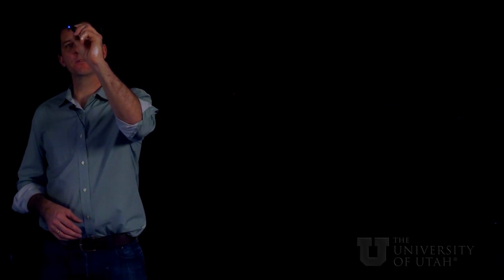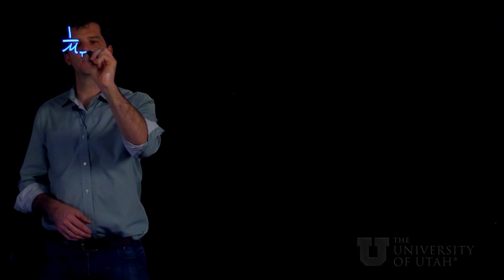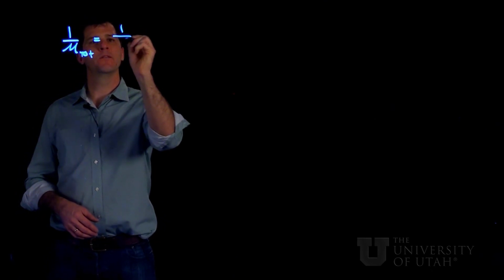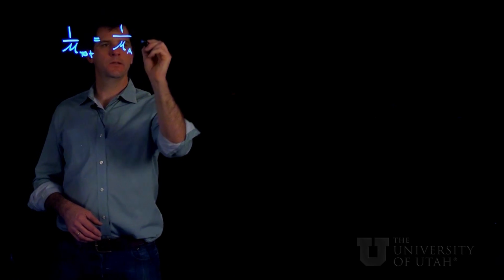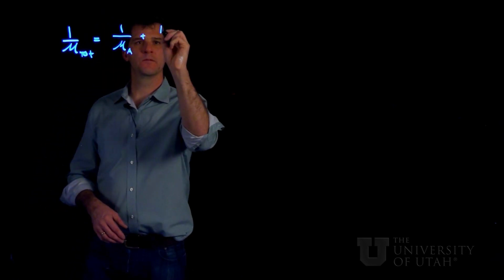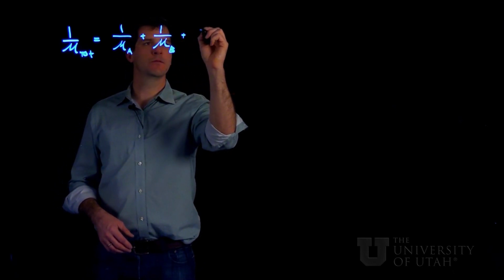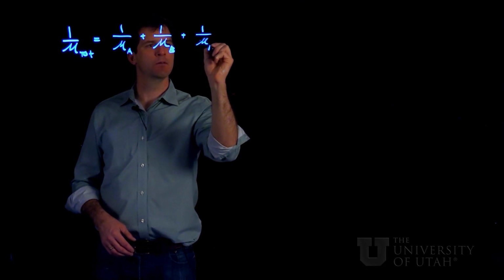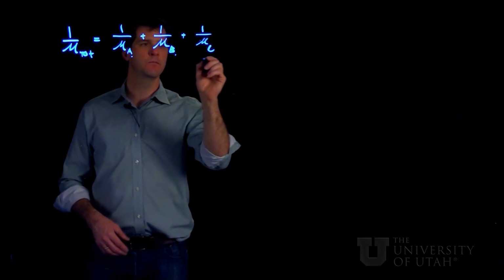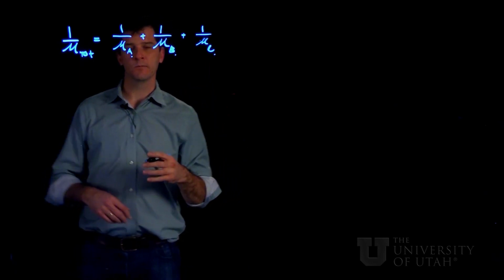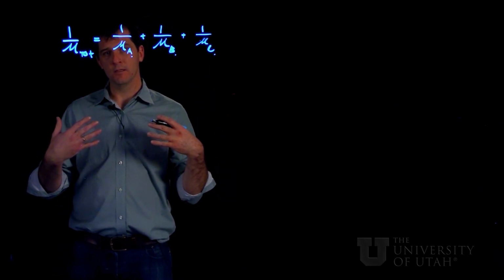So next, let's look at the changes in the physics of transport in the channel. So we have to look back at our definition of mobility. And we have to remember that the mobility is the sum of the mobilities from each different mechanism. So I'm just writing, mechanism A, mechanism B, and mechanism C, where each of these mechanisms is a way of scattering the carriers.